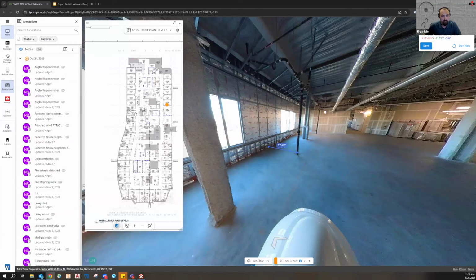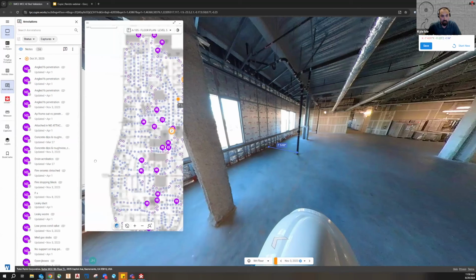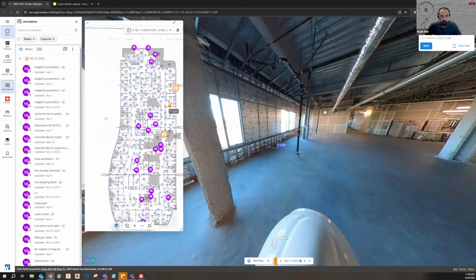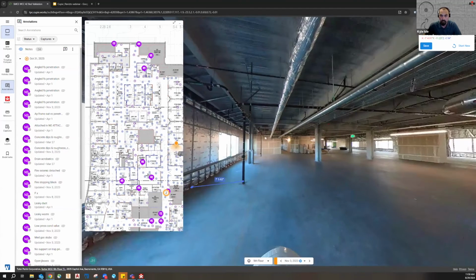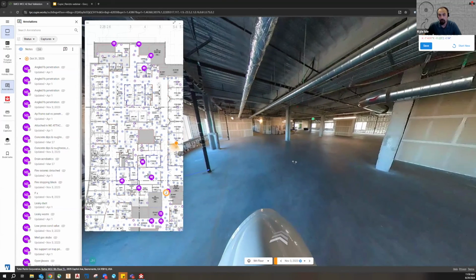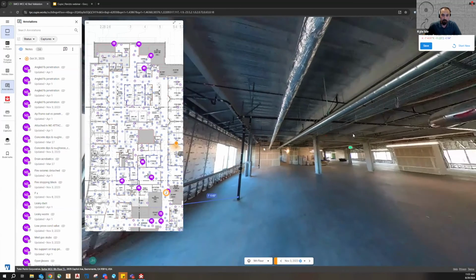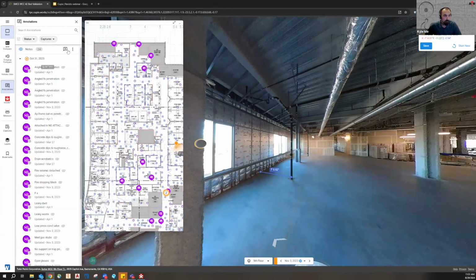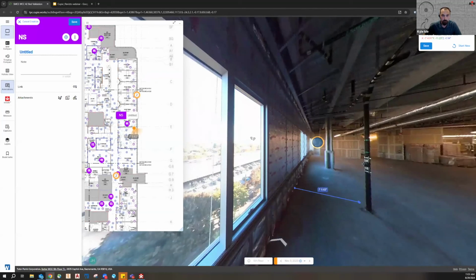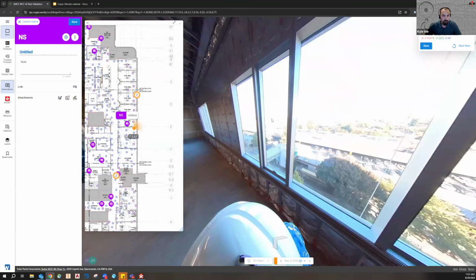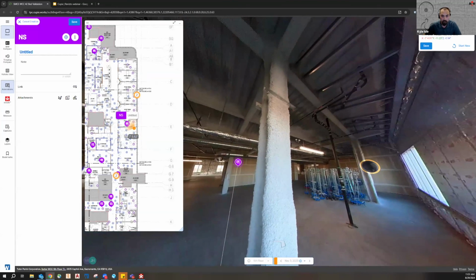So my process essentially is, let's get a floor plan that I've got in Cupix that matches what's in Revizto. And first thing I'm going to do is locate an issue in the capture. In reality, when I was doing this, I was walking the job site and I had found some conflicts. And so, just using my imagination, we're going to drop an issue and call out something that may be wrong. I can see that there's some Z-track attached here that's going to need to be removed before we get started with installation. So I'm going to call that out.